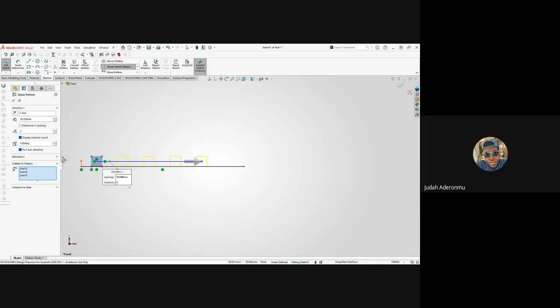But also, let's say I want to create a chessboard now, and I just designed one square. Instead of doing all the top squares and then patterning everything that way, I can just decide to pattern this in 2 directions. Where's my this now?